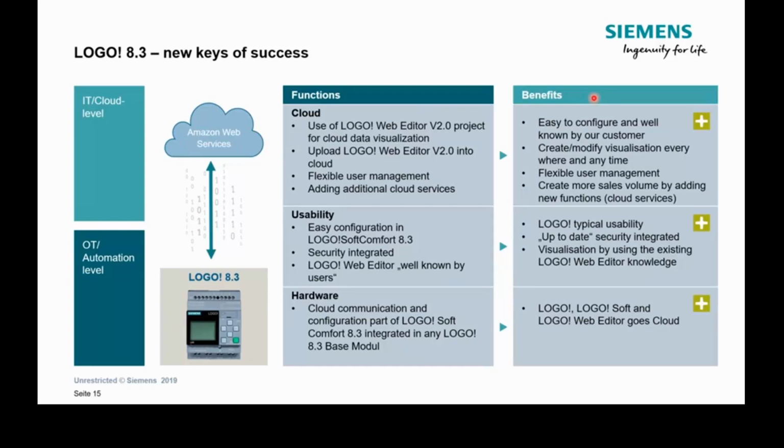You'll get an extra tab of configuration in the properties of the logo where you'll be able to log into your Amazon account and register the logo as a thing on the internet, and then a further tab where you can map the data from things like the timers, as we just did, but push that into the cloud. So you just basically say, I want the timer to be available in the cloud, and it's this one, please. Tick the box and away you go.